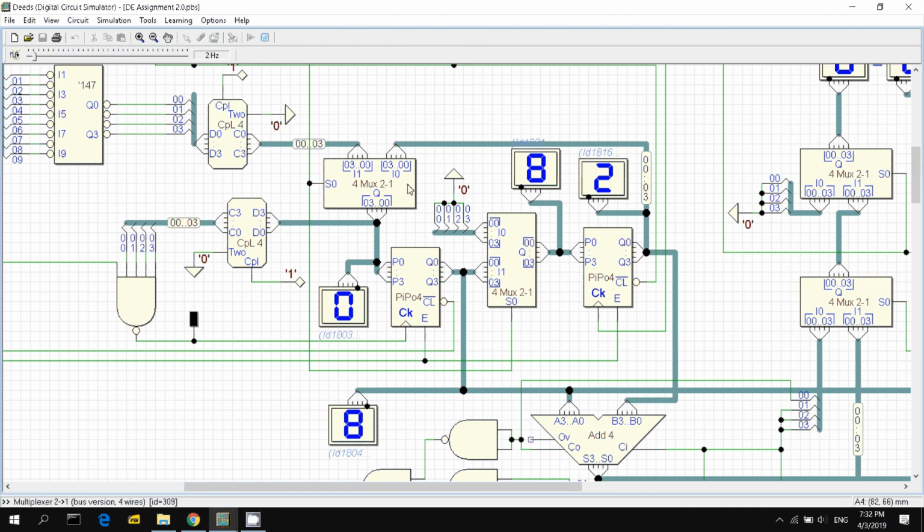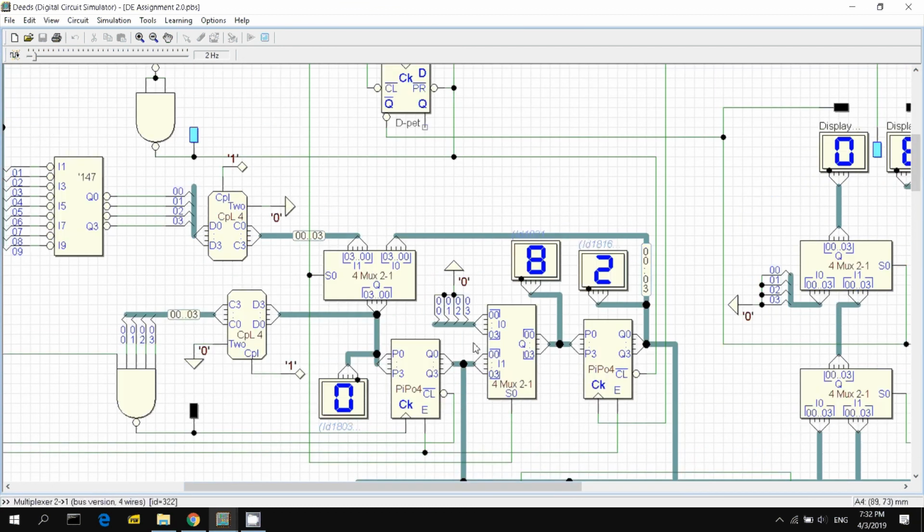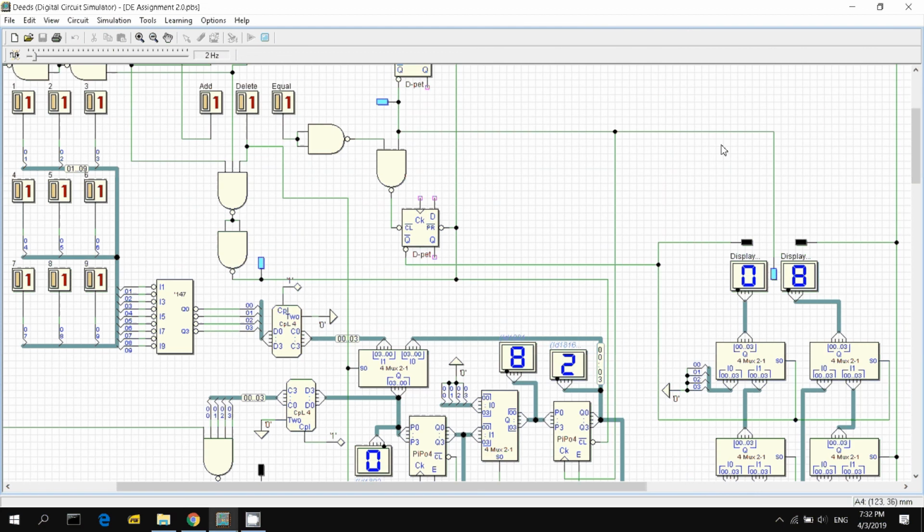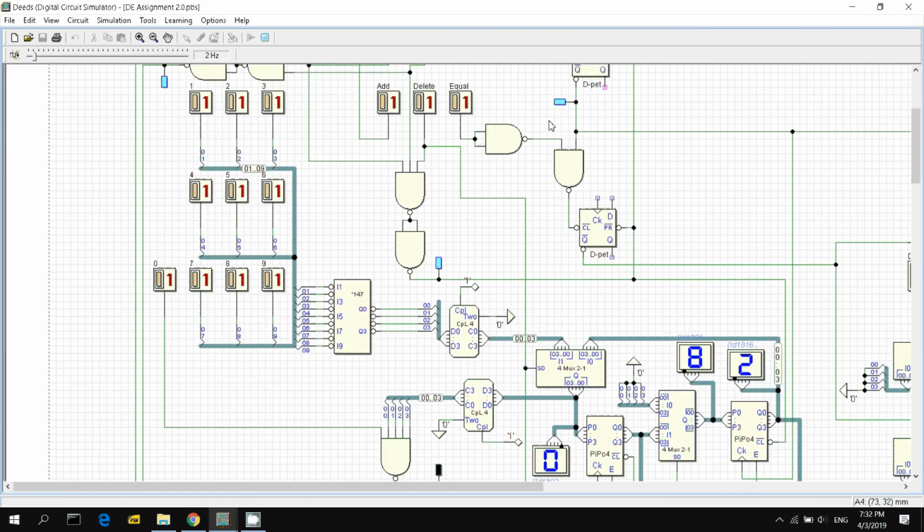and that's for this multiplexer. But at the same time for this multiplexer, when your delete goes to 0, you choose 0, right? Like I told you just now, all the logic here is 0. So this 0 will go into the input of this register, and this register will become 0. So you are moving the 2 to the first register back again, and deleting the first number. Okay, so I show you again.